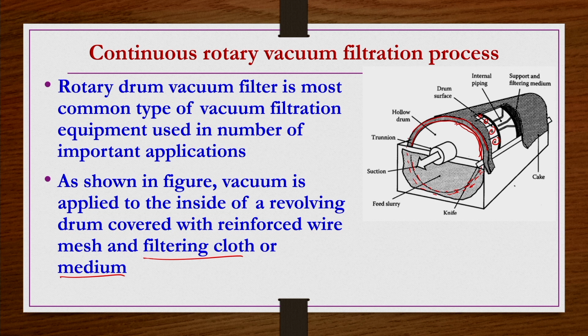Here, this drum is immersed in a feed slurry tank. There is a feed slurry tank, right. In this feed slurry tank, the drum is immersed only to some fraction, it is not immersed completely. So, let us say 50% is immersed now.